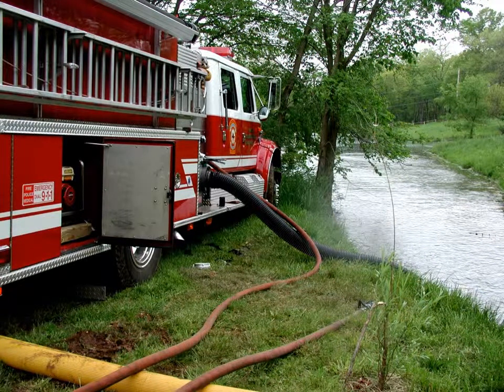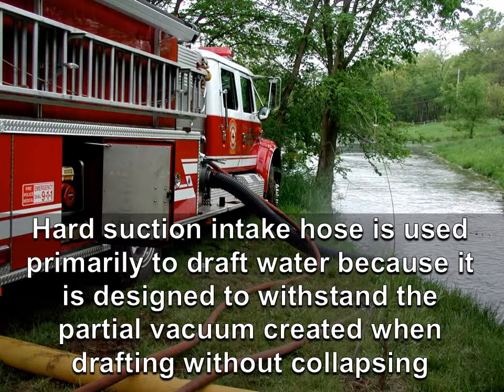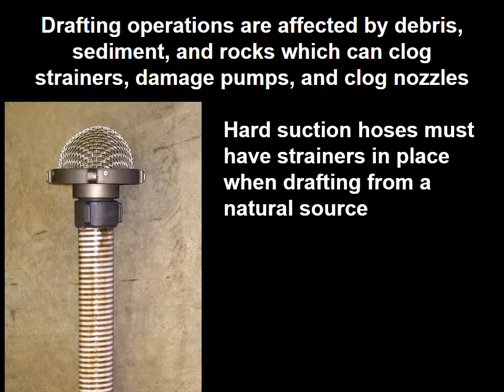Drawing water from a static source to supply a pumper is also known as drafting. Hard suction intake hose is used primarily to draft water because it is designed to withstand the partial vacuum created when drafting without collapse. Drafting operations are affected by debris, sediment, and rocks, which can clog strainers, damage pumps, and clog nozzles. Hard suction hoses must have strainers in place when drafting from a natural source.